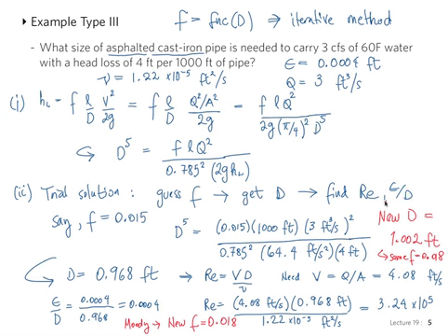But then you have to realize that for this value of D, you actually have to choose something that's commercially available. So you need to choose the closest value that is being manufactured. Probably it's going to be 1 foot, right? You can't just order piping of any diameter that you choose. There are going to be very fixed values that are available commercially.